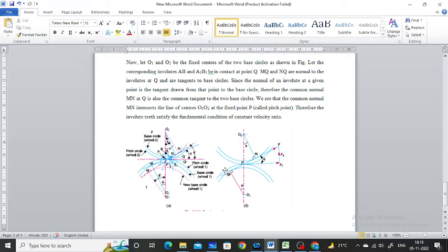Since the cycloidal teeth have wider flanks, the cycloidal gears are stronger than the involute gear for the same pitch. Due to this reason, the cycloidal teeth are preferred especially for cast teeth. Number two: in cycloidal gear, the contact takes place between a convex flank and a concave surface, whereas in involute gear, the convex surfaces are in contact. This results in less wear of cycloidal gear as compared to involute gear. However, the difference in wear is negligible.